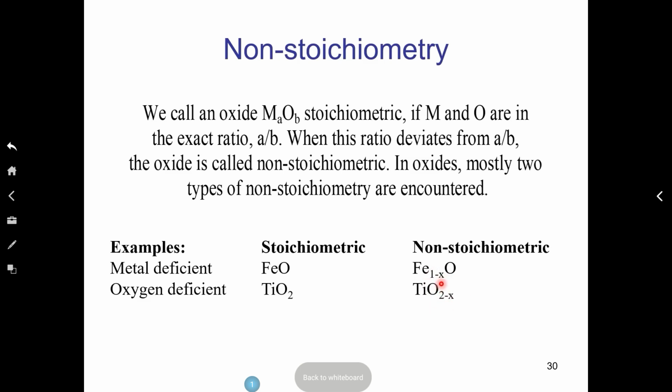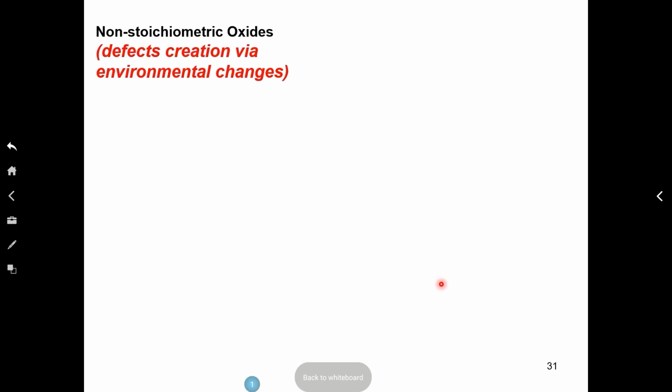And you will see that you are creating vacancies that you could create either by thermal energy or by doping. But instead, you are creating this by controlled environment. That's a cleaner way of doing it. And you can always do this experiment relatively easily in a lab. Question is, how do you control the PO2? We'll talk about that as well.